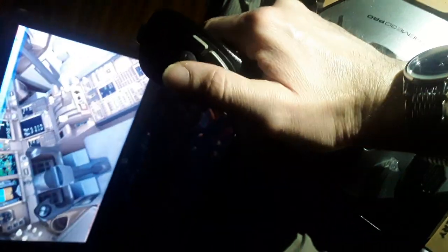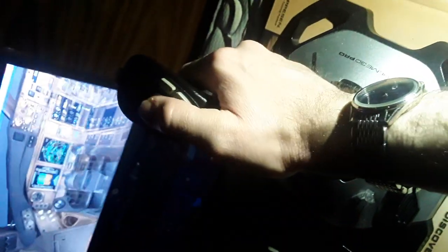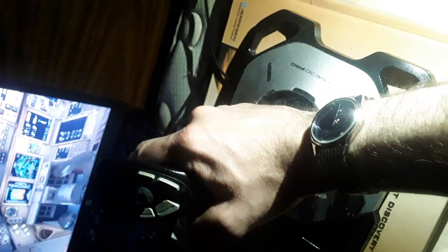So I'm using this side stick. You can see I can climb, I can descend. Using the side stick, I have a proportional input of the side stick position into the yoke of the Boeing 777 airplane. So I can climb, I can descend, I can leave neutral, I can bank roll left, I can bank roll right, and also do a coordinated turn with climb and turn, or the other way, turn to the right, or climb or descend and turn.